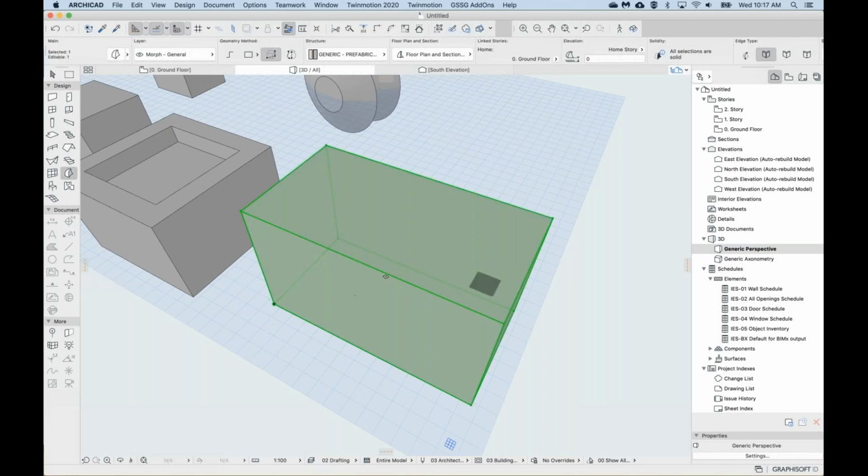So I'm going to hold Shift to select this new brick-shaped morph that I created. I'm just selecting it, and I want to find a third. So when we hover over an edge, we should get a little dash, like a little tick mark in the center of it. So this is a snap point. We got a little tick, but I don't want a center point. I want to break this into thirds. So I want to find where the third points are.